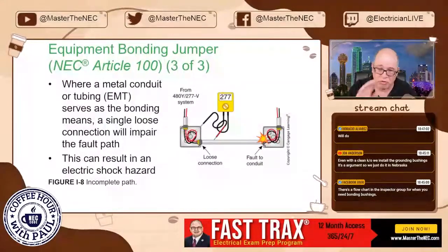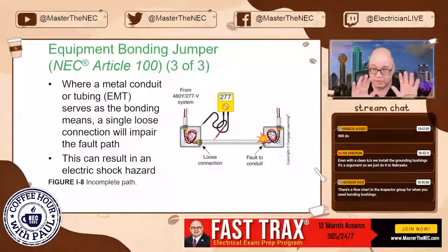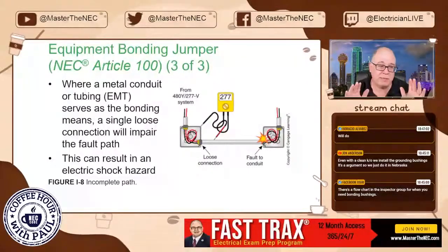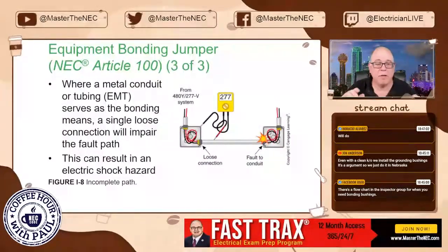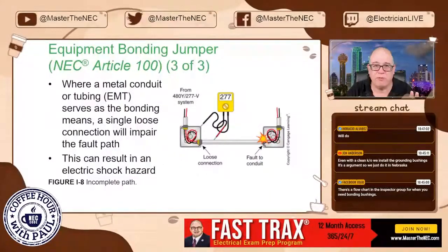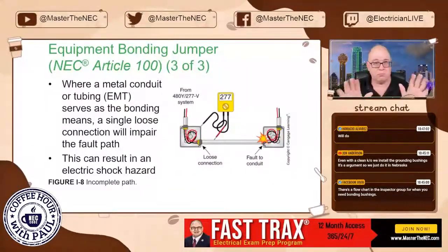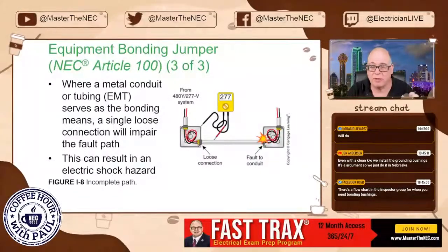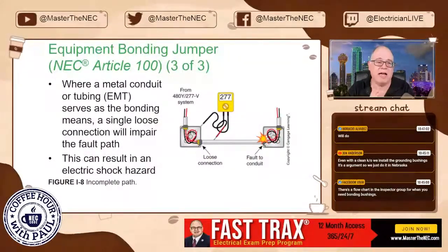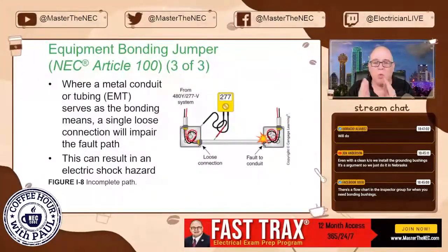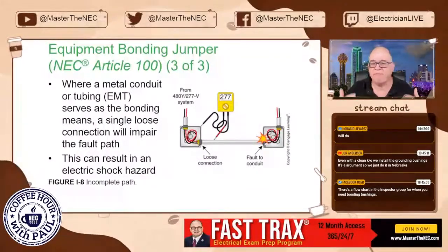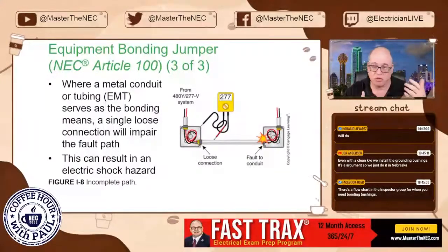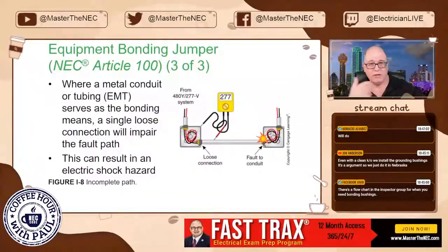Not that you couldn't use the raceway. Look, I don't want the Steel Tubing Institute folks to jump on me. I'm not saying that. The code allows for it in 250.118, so relax if you're out there watching. What I'm saying is that a lot of engineers and designers will want you to put the wire type in there because they feel more confident that you're going to make those terminations, because that's what we're always taught.